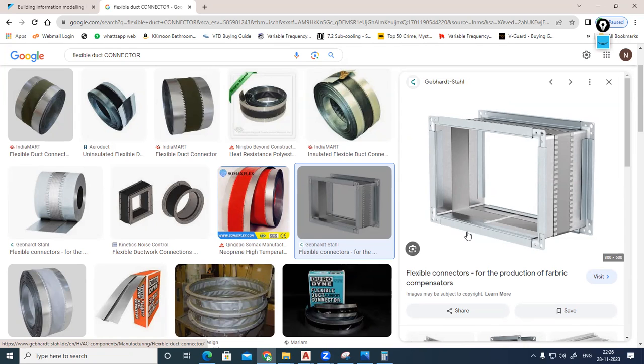The second reason: the machine is rigidly fixed, and the duct is also. So when you are trying to get the alignment between the machine and duct for the bolting connection, you need some flexibility in the machine mouth. Then only will the alignment be achieved. So alignment is one reason, vibration isolation is another reason.